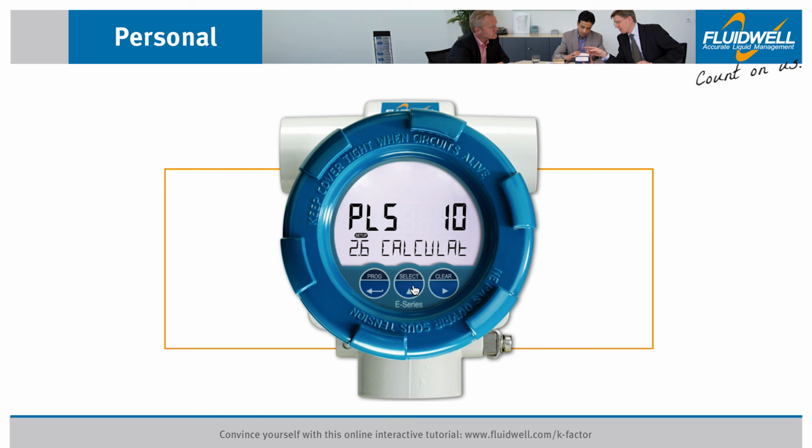The flow rate is calculated by measuring the time between a number of pulses. The more pulses, the more accurate the flow rate will be, but also the response time will decrease. Press Prog to change this setting. We are going to select 10 pulses. Press Prog to store this setting. We have now set the flow rate calculation to 10 pulses per measuring unit.